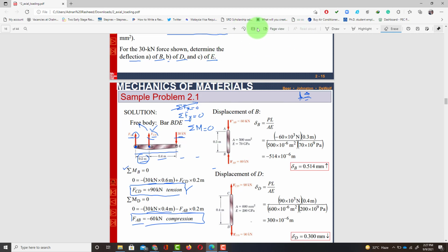So you can see here that this was the link AB, which was over here. Now the force, we assumed that this was upward, but actually the reaction force on this bar is toward downward, and similarly the force on the link will be in the opposite direction, because here you are showing the reaction forces, but the actual force acting on this link AB is upward.